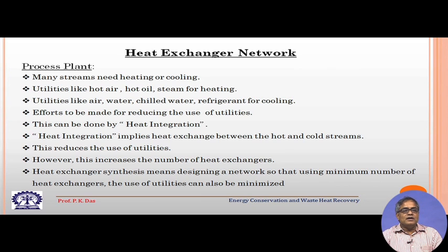If heating is needed, we have to see whether we can do the heating again internally without paying some money for the hot utility. This is called heat integration. Heat integration implies heat exchange between the hot and the cold streams. This reduces the use of utilities.